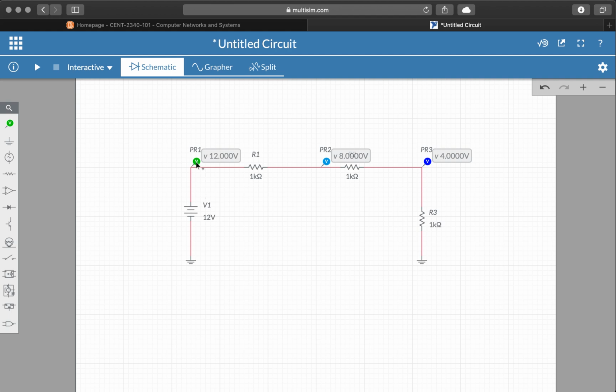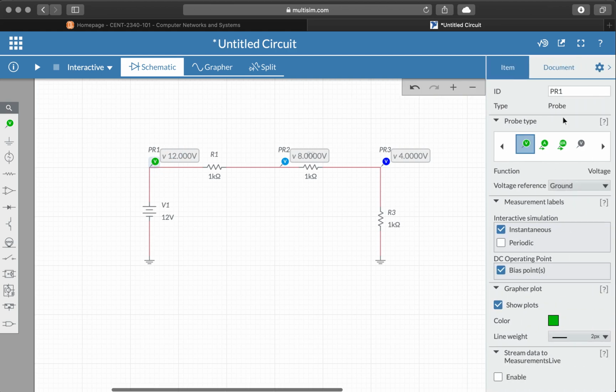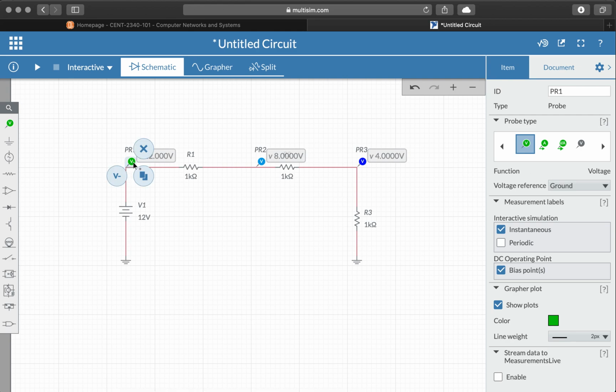So click on the probe that you want to measure with, and I want to show you these settings. I mentioned that all probes are by default associated with ground, but note that if we click the gear icon, we can set the type of the probe, but then we can also set its reference. The only problem is the only reference we have here is ground.